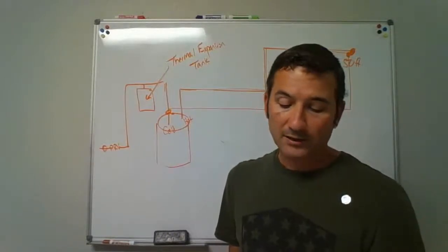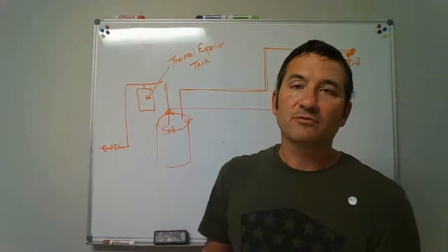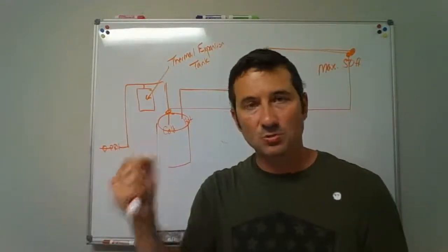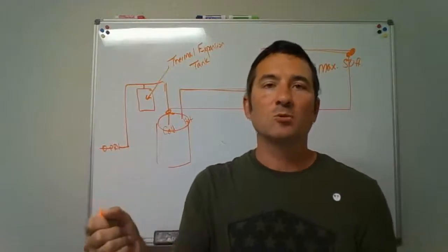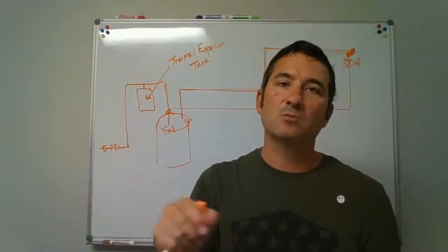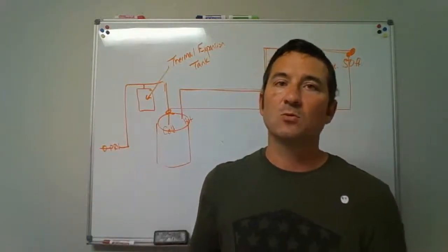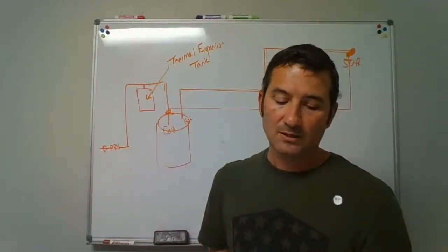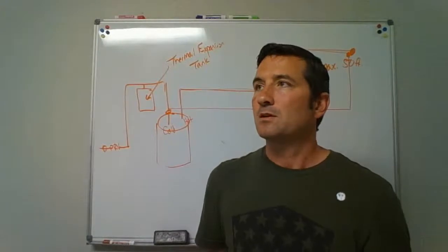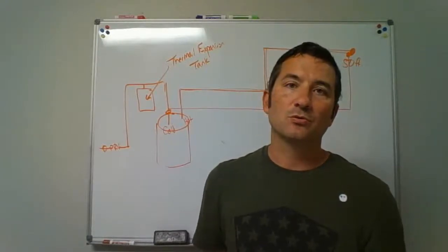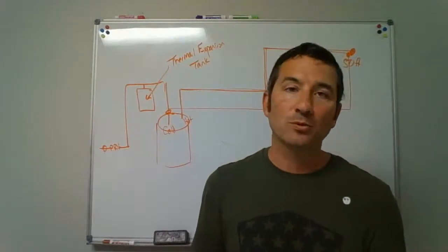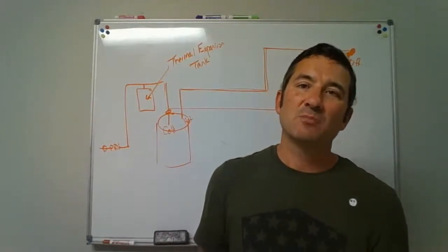You've got to have means of protecting against any type of cross connection, meaning we have a source of known safe drinking water, and we do not want to mix that with a not safe for drinking water to where any type of cross contamination can happen there.